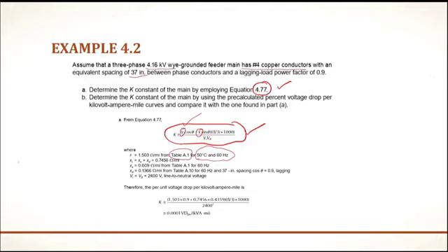As we have discussed that the value of k has been determined using the per phase analysis, we are going to put the value of voltage in terms of phase quantity. This is a three-phase system, so it means that the given voltage is line-to-line voltage. We can simply divide 4.16 kilovolt, that is line-to-line voltage, divided by under root 3. This will give you line to neutral voltage, which is this. So now we know all the values.